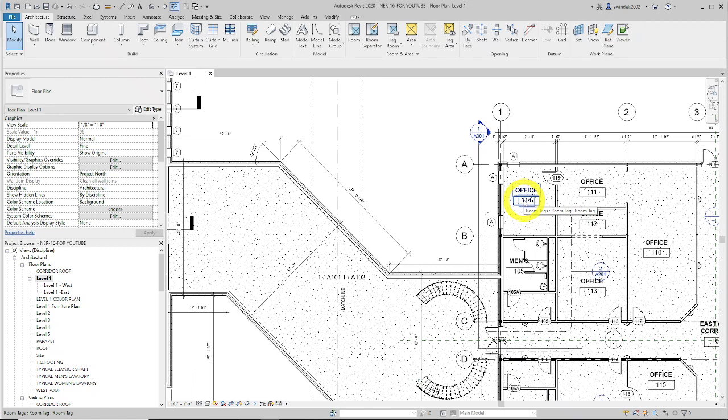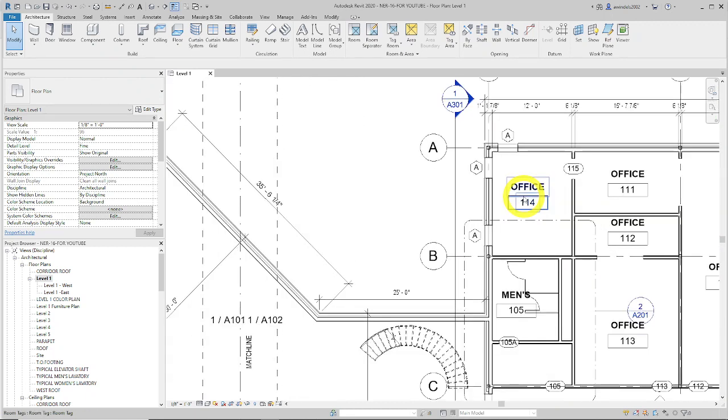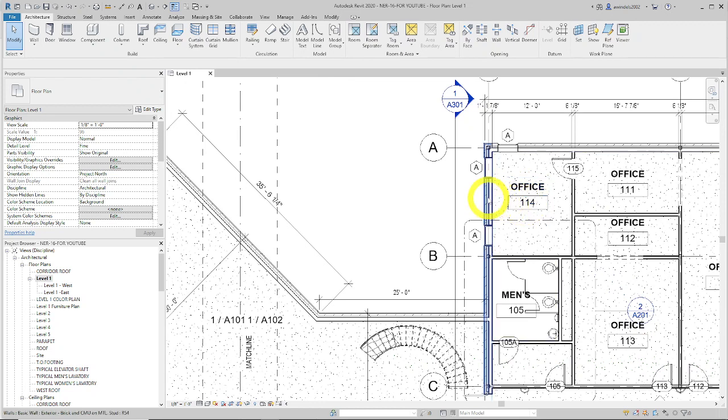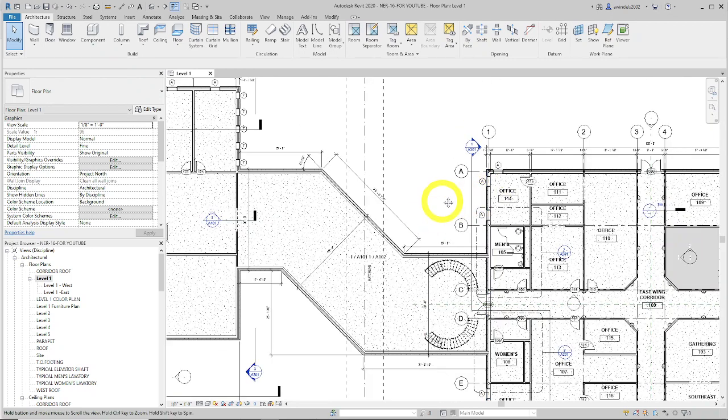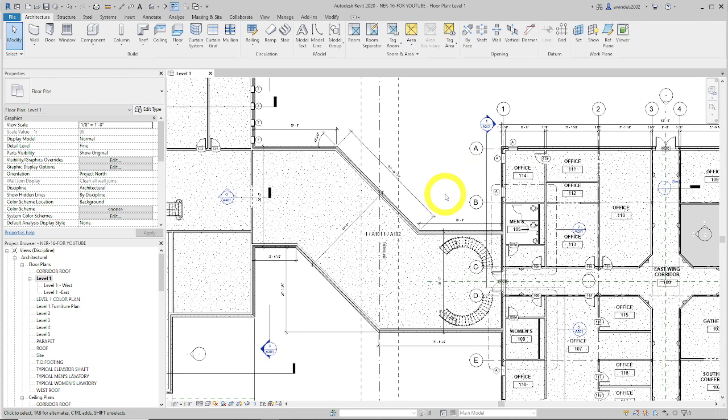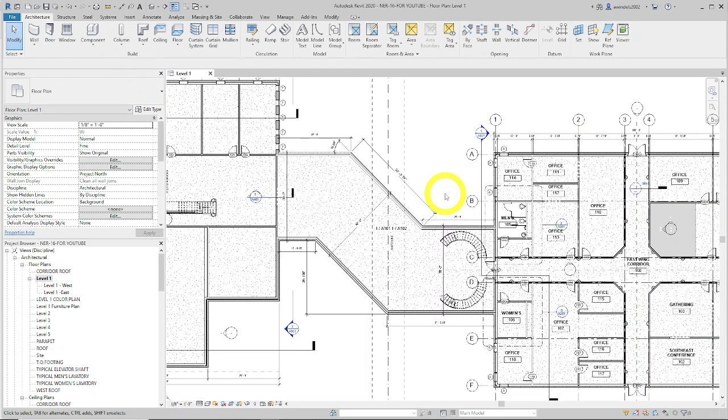And also we're going to go a little deeper to not just doing schedules, but we're going to do material takeoffs. What I mean by that is really deep quantities of materials. So we're going to do something like how many square footage of brick in this wall in this entire project do we have? How many plywood sheets in the entire project we're going to quantify, and that's a lot of times not shown always on a plan set because it's too risky and too much of an encumbrance to try to get correct, to be held liable for a contractor or architects, structural engineers.